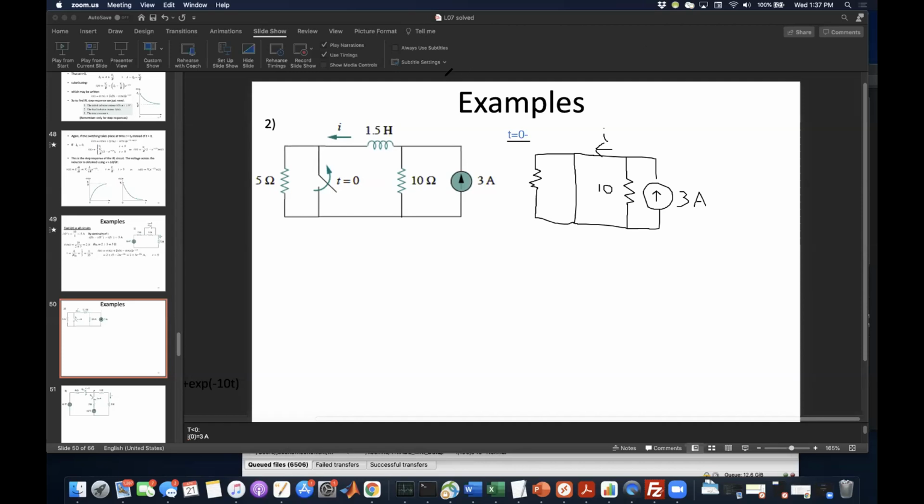Yes, Omar, you're correct. All the 3 amps. That's right, all the 3. And the reason is that the path the current is going to take, and this is one of the only advantages of teaching online, is I can use different colors. The current is going to take this path, because there's no resistance here. And therefore, all of the 3 amps is going to take this path.